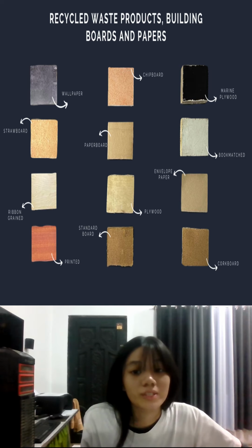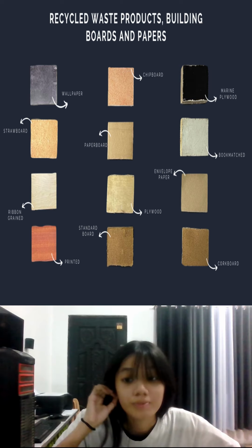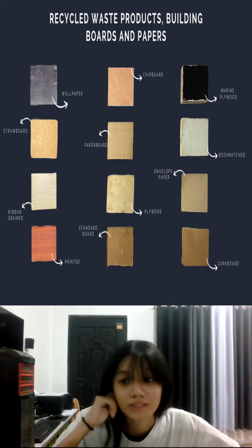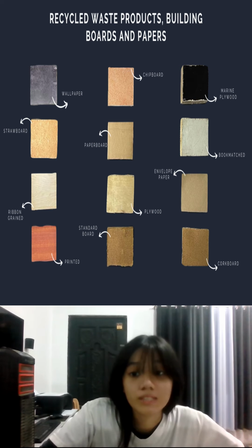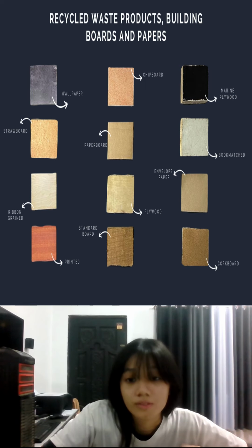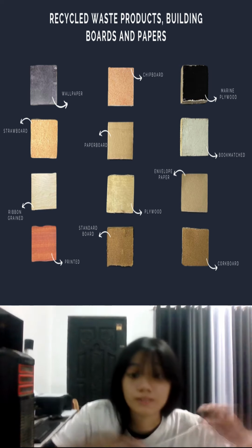So, hardboard. Hardboard is made from processed wood chips. Chips of controlled size are subjected to high pressure steam in pressure vessels. When the pressure is released, the chips explode and the cellulose and lignin are separated from the unwanted elements and then mixed into a homogeneous mass and formed into a continuous board which is cut up into convenient lengths.